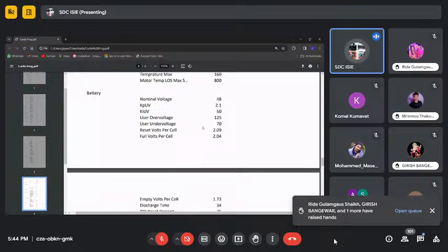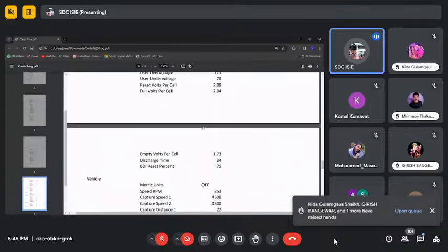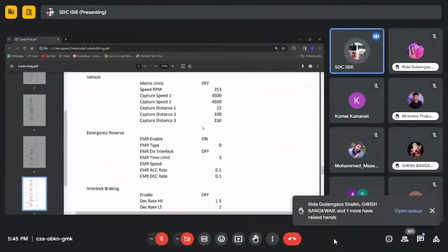In the nominal voltage, we get up to a 48 volt to 80 volt power supply suitable for the AC induction motor, and in AC induction motors we have stator and rotors, but we are not directly connected with the rotors, we use indirect FOC techniques, the field oriented control approach. With it we can change the speed as well as the performance of the motor operations.